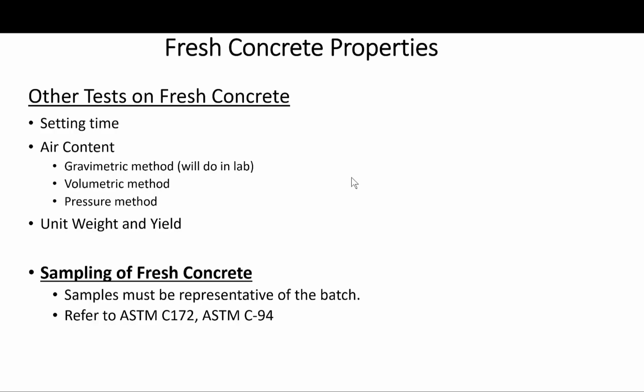Okay, so we're talking about uniformity. This largely becomes significant when using usually older or worn out equipment, or where there is inadequate equipment maintenance, where you might have variation within the batch itself. There are stringent requirements for the permissible variations of ready mixed concrete in ASTM C94.